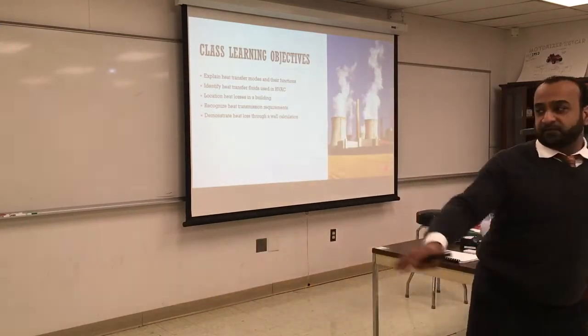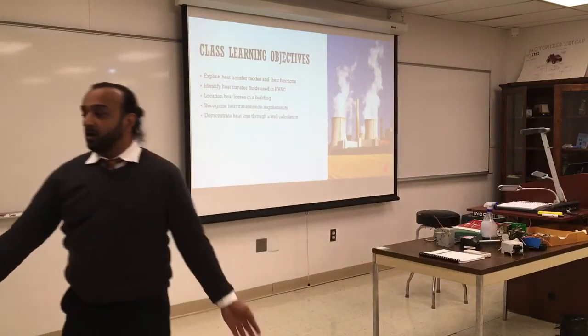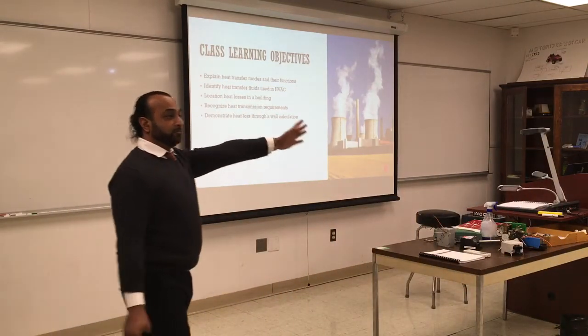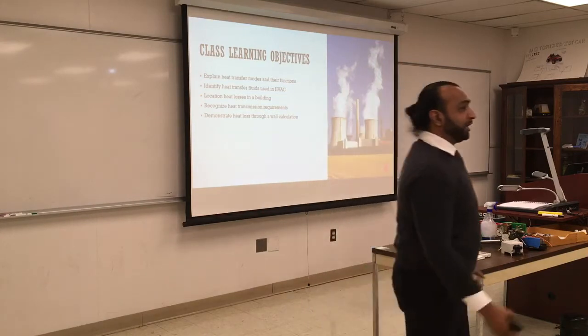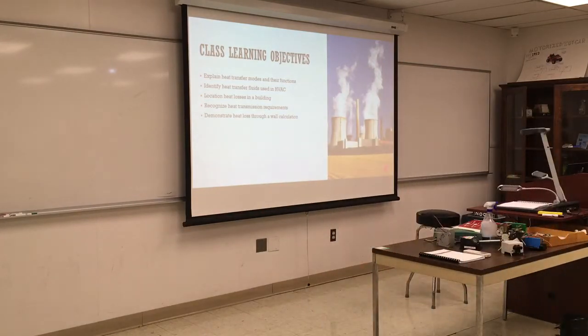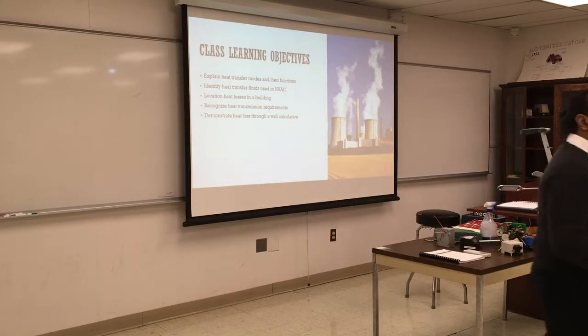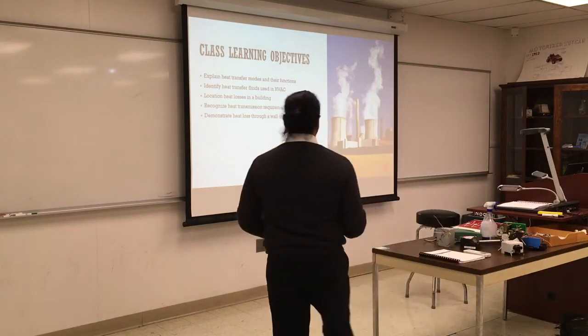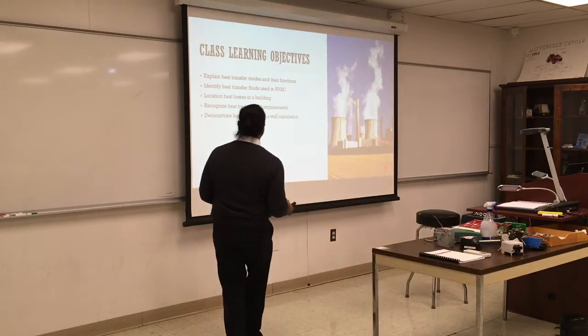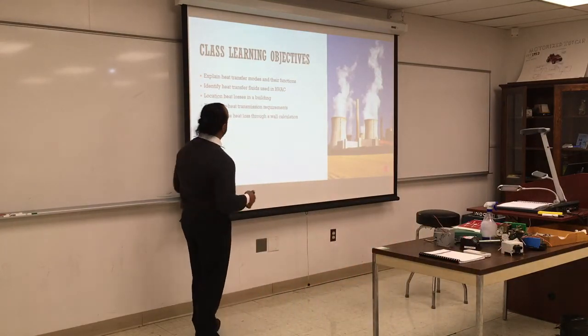So to move the heat from the boiler over here all the way to the room, how are we going to do that? Water. Can you use water? What else? Steam. You can use warm air. Excellent. And sometimes you can use glycol for a hot water system if you want to prevent freezing. So there are some differences between those fluids, advantages and disadvantages. We'll touch base on the science behind it, but I'm not going to go too deep.